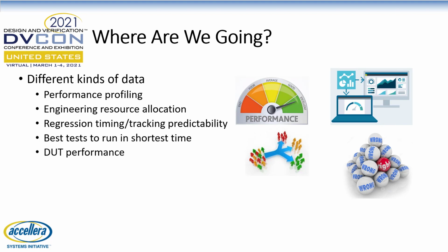And of course, we want to make sure that the design will ultimately operate as intended, so profiling DUT performance can help you find specific problems. We had one design we were analyzing with a prototype, and it reported a performance problem. There were some bus operations that took a really long time. They worked in the sense that the data was properly transferred eventually, but we were able to zero in on the problem, and it turned out that there was a bug in the cache controller.